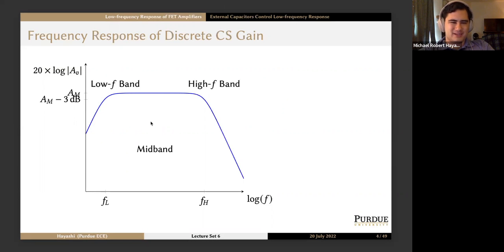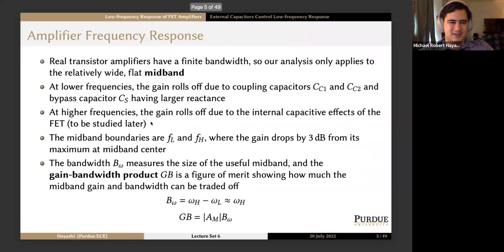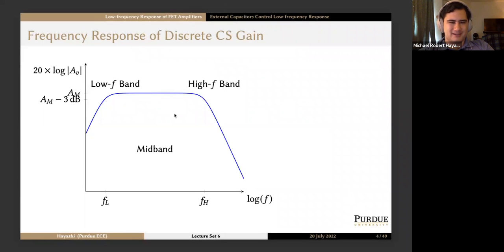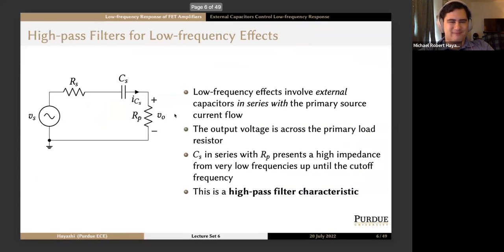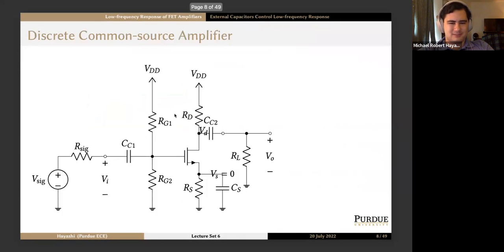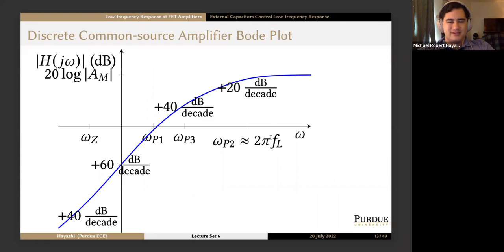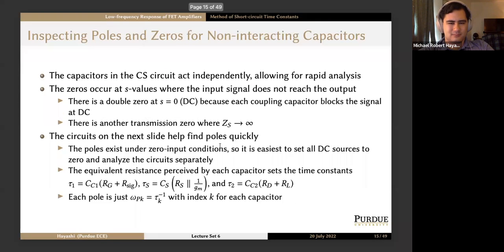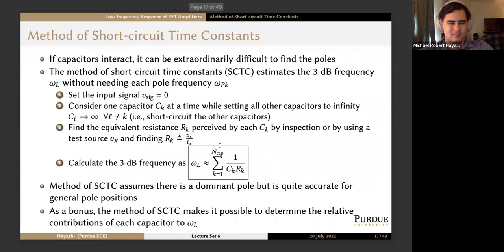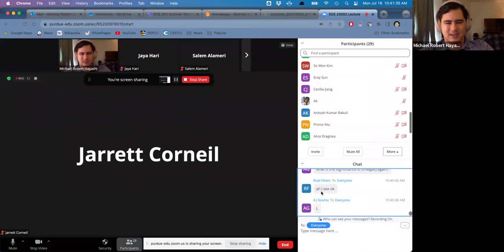This is important because it's one of our boundary frequencies for the mid band, and it helps define where the transition of behavior in the circuit happens. So we say omega L is basically the same as our highest pole. Any more questions?